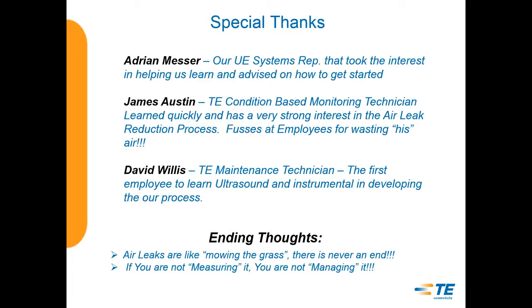That's pretty much it. I do have a couple of thank yous I'd like to throw out there. Adrian Messer was one of our UE sales reps at the time. Instead of just selling us a gun and then giving us a call a month or two later, he came in and made sure we all had a good basic understanding of it. He helped us understand how important it was to get someone certified on how to use it. One of the biggest things we didn't understand at the time was that he told us to go out and find all the 70, 80 decibel air leaks first, fix those, and then you can hear the smaller ones.